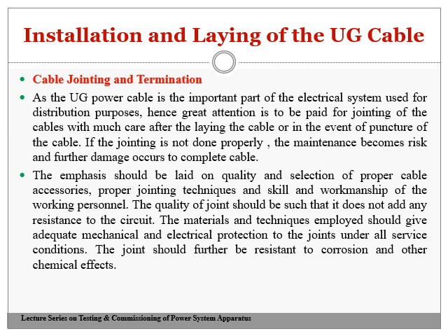If anyone is not taken care of, the jointing becomes improper. Automatically, after a few days or a few months, the same joint may burst out or get punctured. Once again, repetition of work takes place. That's why we give much importance to jointing with the above factors. The quality of the joint should be such that it does not add any resistance to the circuit. One more point to be considered is that when you have a jointing structure in the middle of the cable, it should not add additional resistance.